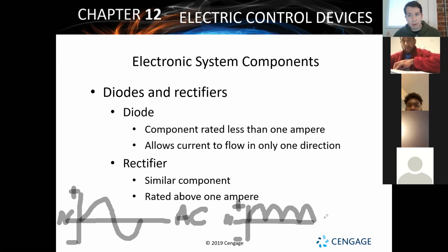But for the past 10 years or so, especially residentially, it's becoming much more common to see modulating control, where everything comes in as AC electricity, gets changed to DC electricity, and then instead of 0 or 100 for the single speed, or 50% and 100% for the 2-speed, now we have modulating.